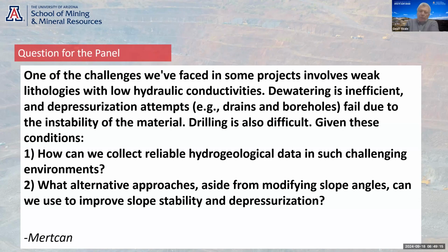I mean, there are a couple of large open pit coal projects that I've been involved in over the years where you've got very low permeability clay in the slopes, and we've gone in with a drain spacing of 5 meters over a large slope just to get it depressurized and to gain 10 degrees on the slope. On a big pit, 10 degrees will pay for any depressurization.